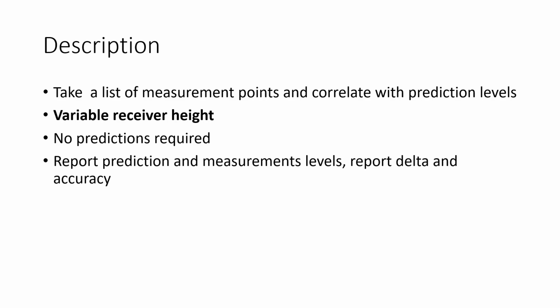Most of the measurements usually have fixed elevation. You're doing drive tests 1.5 meters above the ground or something like that. But this feature is accepting variable receiver height, which means you could apply it for drones, if you're using drones for measurements or for validation of the antenna radiation pattern.